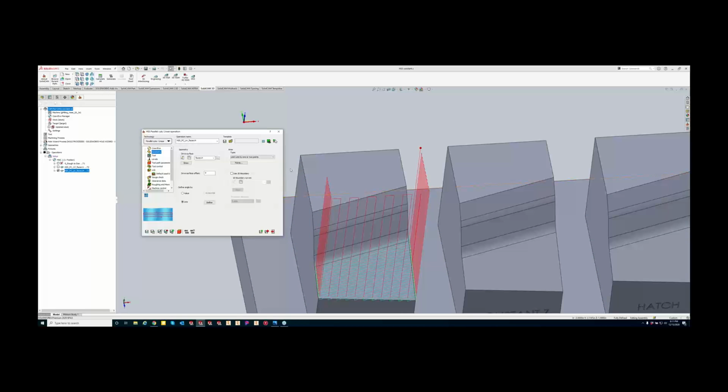So that's a nice way to fine tune your tool path. We can also do a 2D boundary at that point, but that would involve creating a sketch, manually sketching something in there, or grabbing geometry that's already on the part. Tool, we know how to do that. Levels, by default, is set to automatic, so it's just going to do automatically what it thinks it needs to do. You do have the option in here to do plane, and since we are working off a plane, that's what it should be going to. But this is all your clearance data right here.